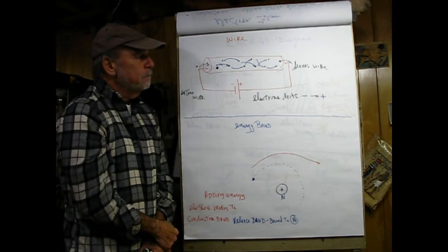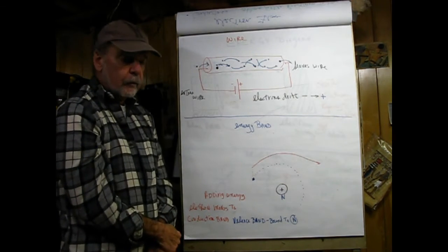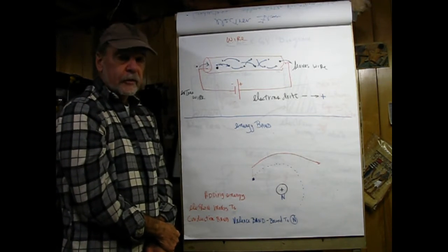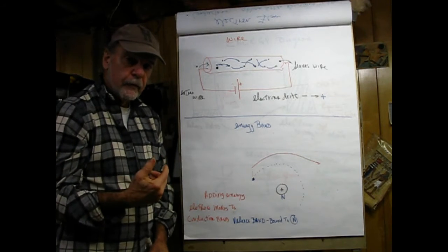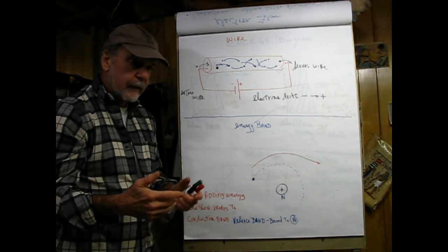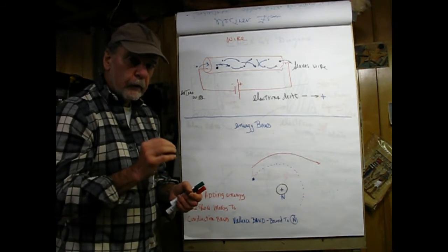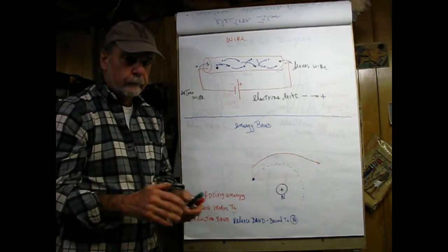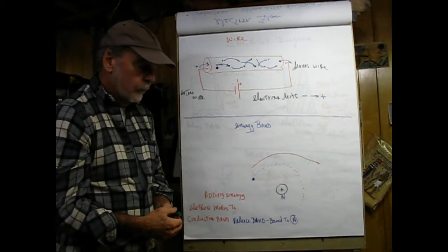So, in the process of forcing these electrons to hop around in here, even though it's a good conductor, energy has to be accounted for, and that is dissipated in the form of heat. So in every wire in your house which is drawing some kind of current, say a light circuit, the wires in the wall are slightly warm. Now, if the wires are sized correctly, it's no problem. If they're not sized correctly, well, you can burn your house down.